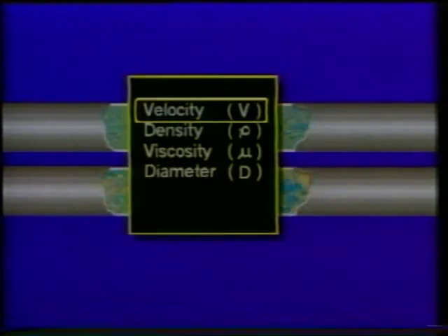Turbulent flow is characterized by eddies that cause complete mixing of the fluid. There are no distinguishable layers. The velocity profile for turbulent flow is relatively flat. As the overall velocity of a given fluid stream is increased, a point is reached where flow makes a transition from laminar to turbulent. Of course, velocity is only one of several factors that affect the type of flow that will occur in a system.